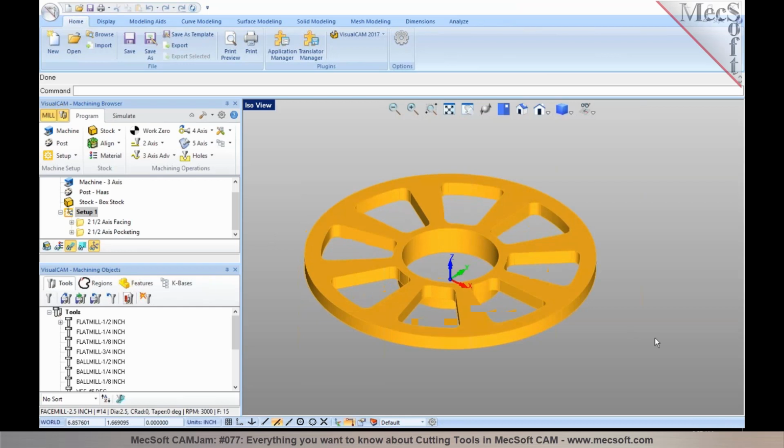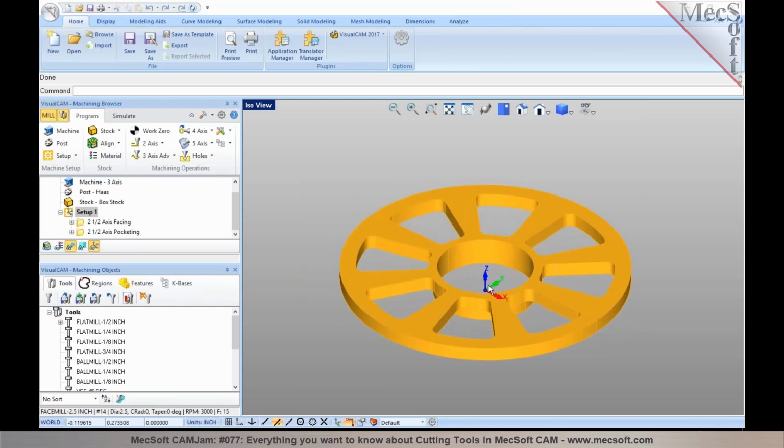Those are the areas where you can optimize it most, because most of the time the cutting feed rates are pretty much based on the material and the tool. And then of course, as Uday pointed out, step overs and cut depths will affect the length of the overall motions. So these are the only two ways you can do it. Hope that makes sense.